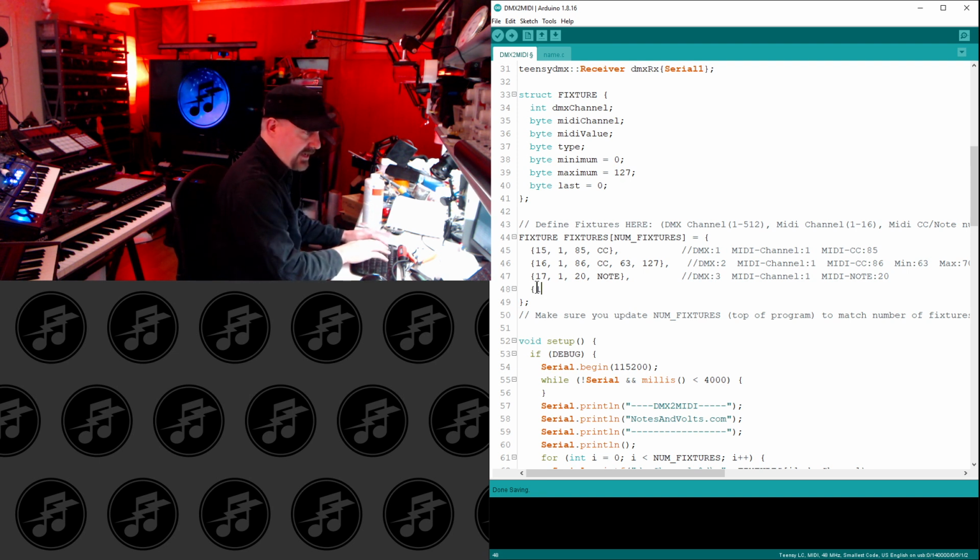So we could do like 18, channel 2, number 120, and it's a CC. End it with a curly bracket, and if it's the last fixture, you don't need the comma, but you could add one anyway if you like.